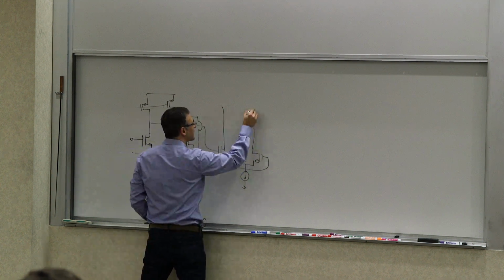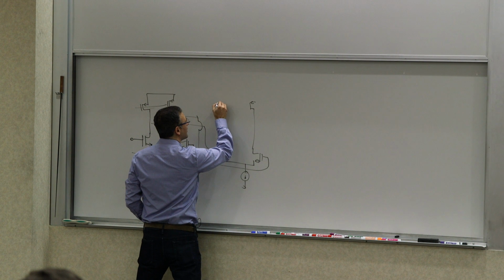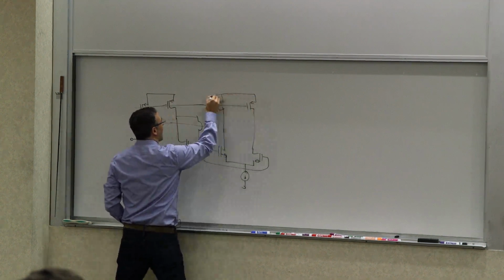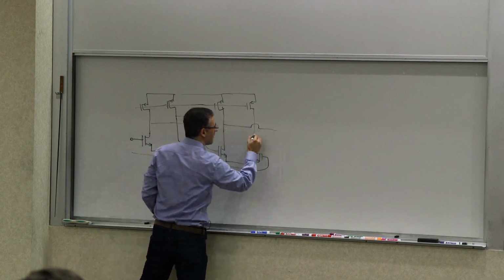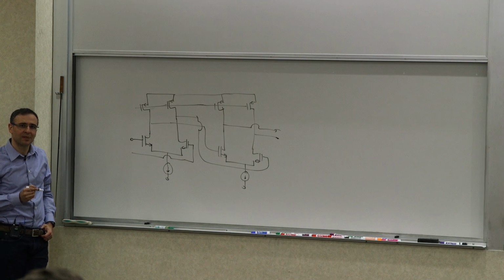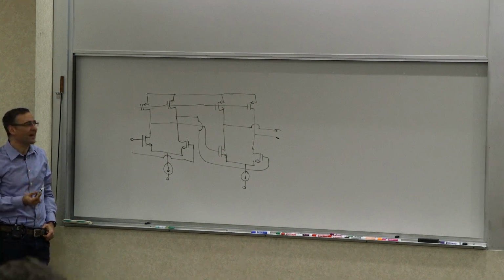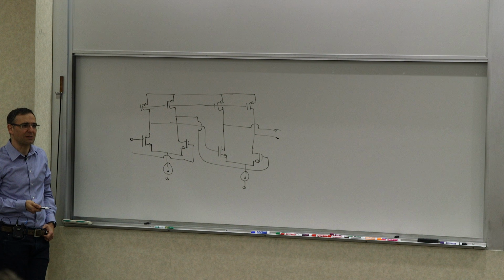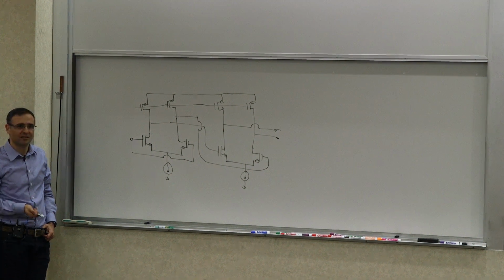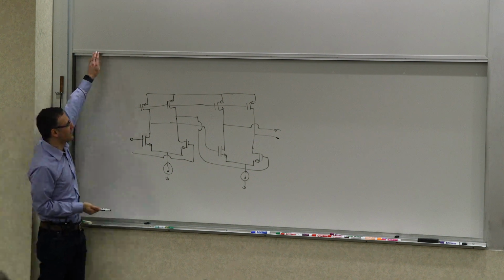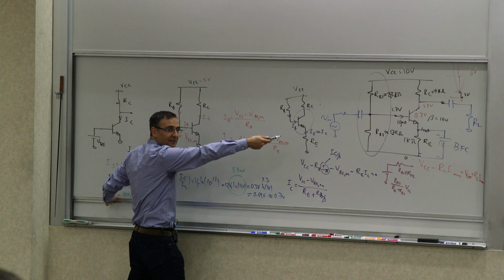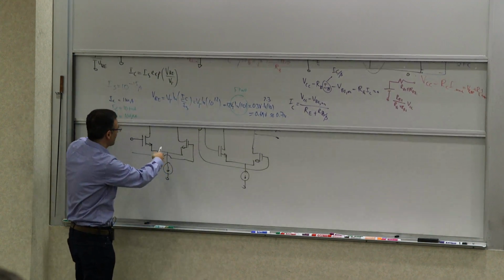And you can repeat these things without having to worry too much about coupling. This allows you to create a DC coupled system. This is an artifact of the fact that capacitors are expensive and transistors are cheap on integrated circuits.